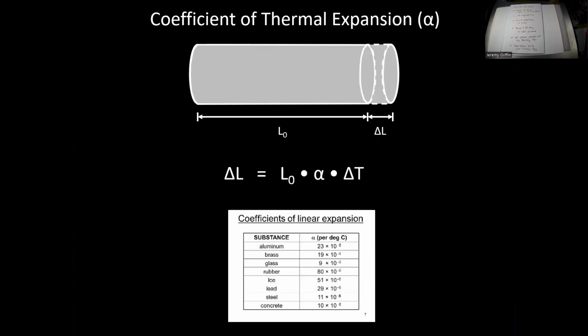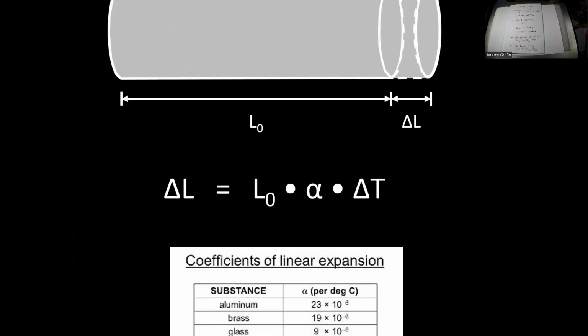You know what else could expand something is a temperature change. I think we talked about this a little bit last week. So thermal expansion. How much does something want to expand because of a temperature rise? Well, how much does the temperature rise? Delta T, be it in degrees Celsius, Kelvin, degrees Fahrenheit, as long as you know what you're working with. What was the original length? And what is the coefficient of thermal expansion? That's alpha in this context, the coefficient of thermal expansion.